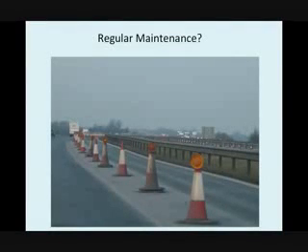Regular maintenance is something else as well. Within Chapter 8 it states that cones, signs and traffic management equipment should be kept up to standard in a nature which gives correct direction for the motorist in all conditions, including at night when there's darkness and there's no daylight. The reflective sleeves shouldn't be dirty, so they reflect back at the motorist.